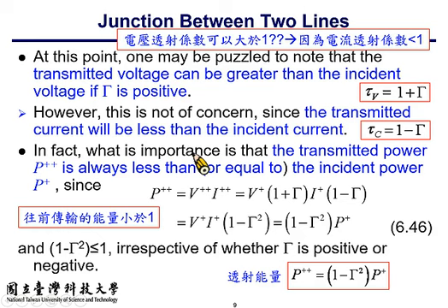is less than 1, your signal gets weaker and your available power gets smaller. So this is a basic principle of circuit design, which we can examine from the perspective of available power. So from this equation we know that for a passive transmission line component or passive circuit, the available power is no greater than the incident power. You can only get a fraction of what is available for your following stage in terms of the transmitted power.